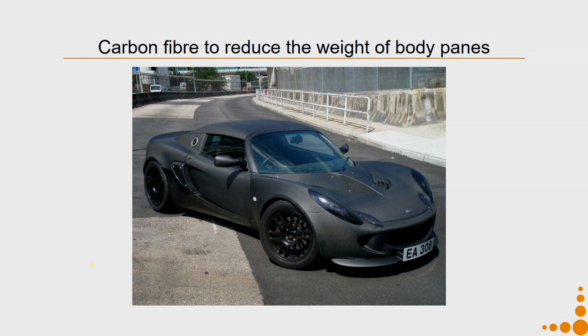Plastics reinforced with carbon fibers are a good material for that, in that they offer a higher strength to weight ratio. What it implies is, for the strength required, the weight of carbon fiber panels is much lower than the metal panels. Of course, this is a more expensive material, hence not all our vehicles can be made of carbon fiber bodies.